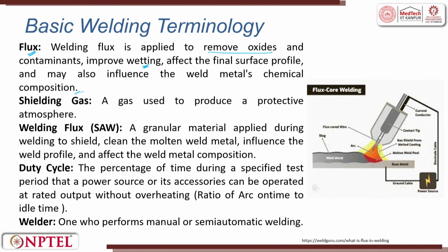What is wetting here? When a metal flows on top of another metal, there is a phase change, solid to liquid, or an X metal and a Y metal. So, there is a difference, and then a surface phenomenon plays a very important role. This surface phenomenon has to be removed and the metal has to spread uniformly.